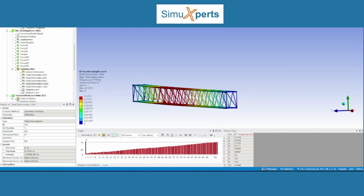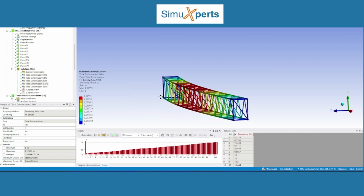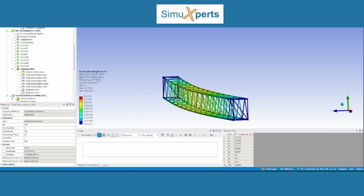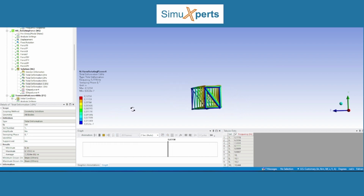And how I like to look at this is by almost being aligned with the x direction, but not quite, as we see here on the screen. So let me just zoom in a little bit, and let's animate this. What do we see? We see a motion that's mainly in the Z direction along the weak axis, because right now we're below the first natural frequency of 10 Hertz, which occurs around the weak axis, and we're quite far from the first mode around the strong axis, or the first mode in the Y direction, which is at 14 Hertz.